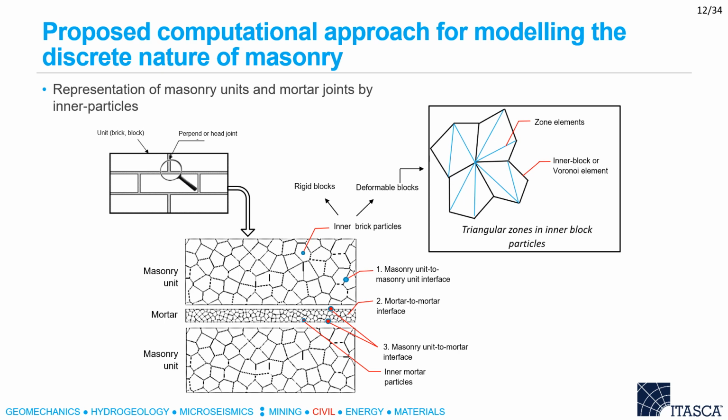In this study, an alternative approach for modeling the discrete nature of masonry subjected to direct compression has been developed. In the proposed modeling approach, the microstructure of masonry units and mortar was modeled as an assemblage of densely packed, irregular in shape and size discrete elements bonded together by a zero-thickness interface. Such irregular elements could be a few millimeters in size and are able to move independently of each other, open, close, or slide. In this way, cracking can be allowed in either brick, mortar and/or brick-mortar interface.